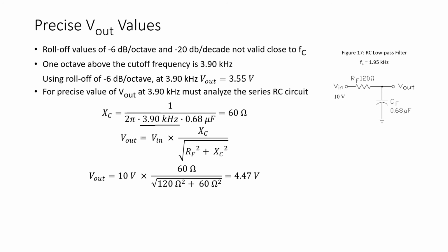So in this presentation, we looked at plots of X sub C and X sub L as a function of frequency, and we used those plots to look at RC and RL filter circuits to determine whether they would function as low pass or high pass filters. Then we looked at the calculations needed to determine the cutoff frequency of low pass and high pass RC filters, and calculate the cutoff frequency for low pass and high pass RL filters.